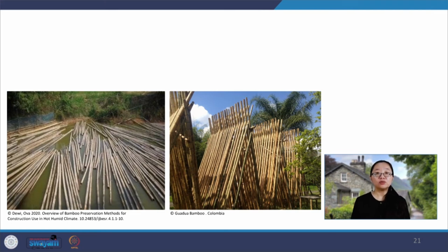So to guarantee durability in bamboo construction, it is important to take into account good procedures of cutting and curing or drying bamboo. The first is cutting. Cutting bamboo is done with a machete or saw directly above the first or second above-ground node, keeping in mind that the cut should be inclined to avoid the penetration of rain into the rhizome, thereby rotting it. It is advisable to make the cut during the dry season when the stems have minimum humidity.